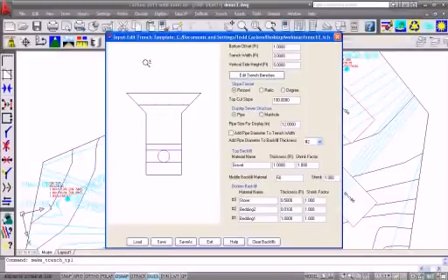So once they get that, we can essentially not only create the trench, but we can size it to the exact design that we want it to be with all of the materials added, which you're filling in at the bottom there with maybe crushed gravel and so on and so forth. Right, yeah. So what this is going to do is give us complete volumes for the stone, bedding, and gravel that we've defined here, a lot more sophisticated than just looking at the plan and estimating by the distance of the pipe, because the depth of the pipe is changing, so some of these materials are going to change depending on the depth and the width of the pipe.